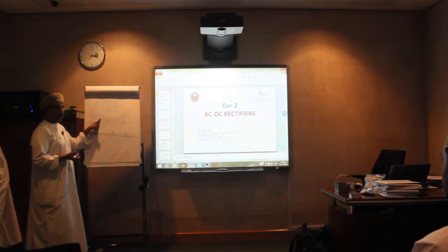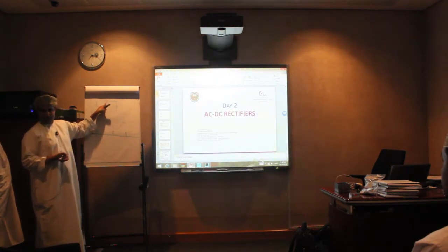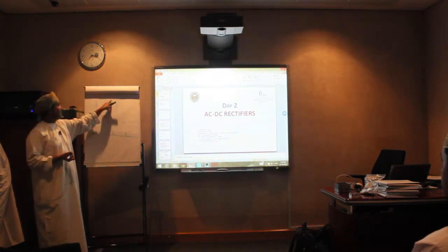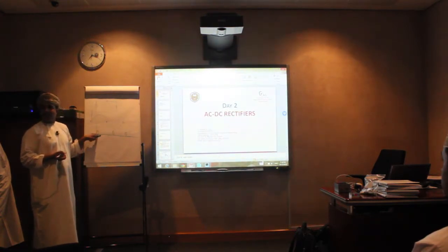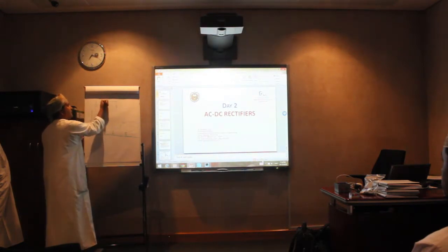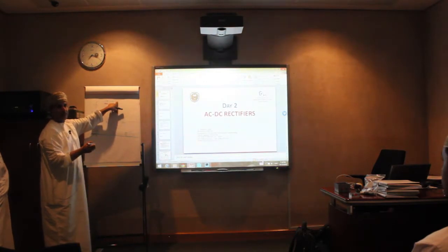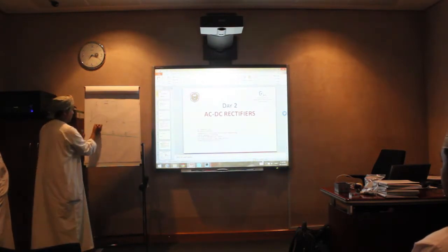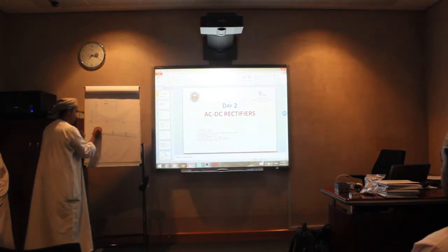And then after that, the thyristor is still in forward bias, right? But I send the current signal, which is this one, so the thyristor will turn on. If the thyristor turns on, that means it conducts. So what's the voltage between this and this? Same. So I will get the voltage. The voltage will be the same from here to here, so the voltage will jump like this,